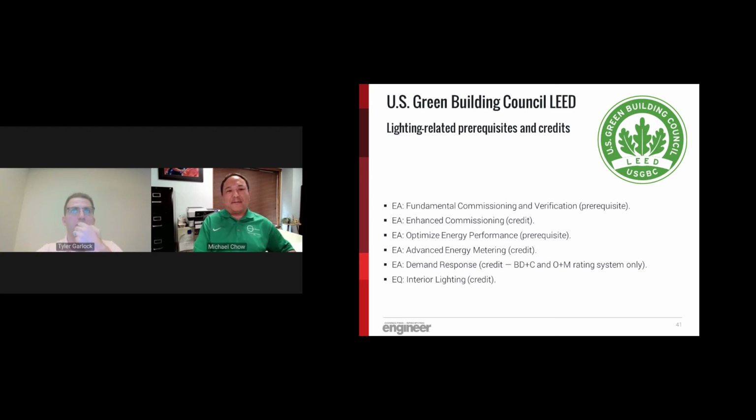And it turns out that the contractor had jumpered the lighting controller, which controls all the indoor and outdoor lighting. And they jumpered it so the lights were on all the time. He did that for testing purposes, and he never remembered to take the jumper out. So with the fundamental commissioning, it was actually commissioned and working properly. But after the commissioning was done, the contractor had gone back and they were troubleshooting, I think, an occupancy sensor, and they inadvertently left that jumper on. So having that separate meter was good because it helped us realize that there was something wrong with the operations of the lighting.